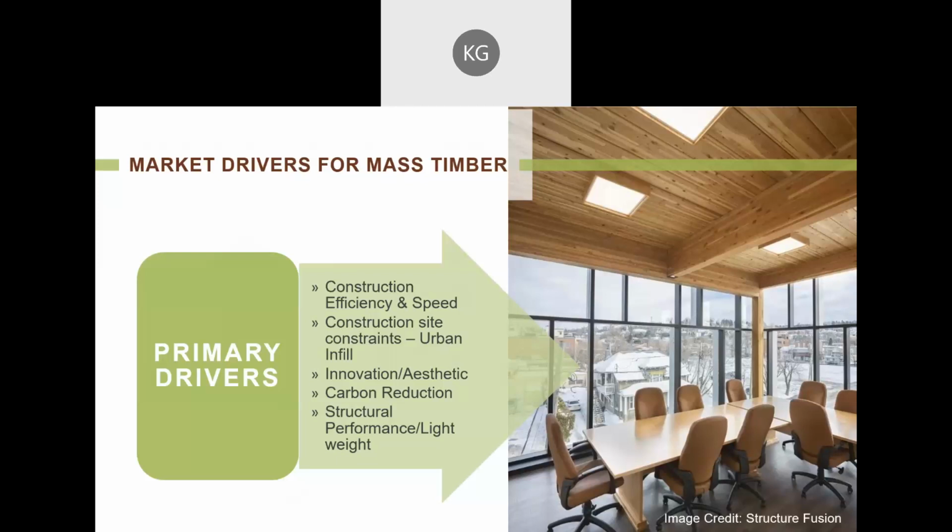Additionally, if you've got a tight site, mass timber works really well because often the crane is just picking the pieces right off the truck as it comes in and putting them right in place. There's not a lot of storage needed. And obviously it's innovative, it's new, it's got a great aesthetic, people love it. And then it's got a sustainability story, and we'll talk a little bit about sustainability in a minute, but it's definitely a perk and a driver for most folks. And then it's got great structural performance in relation to its weight. It's a very lightweight structure.